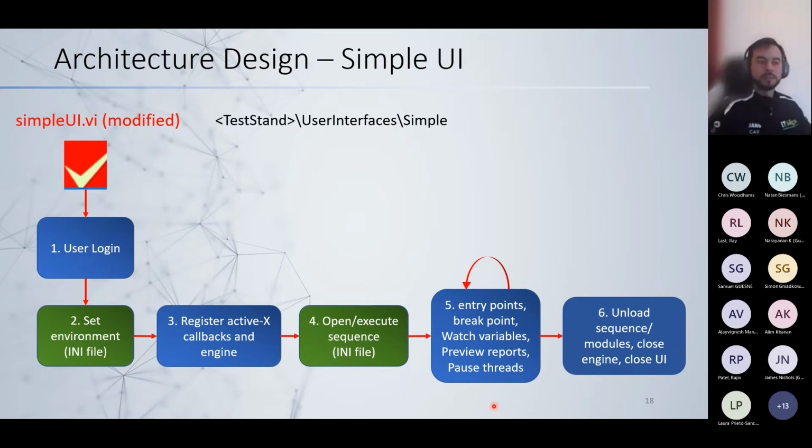Lastly, if you want to shut down your application, there's more modification I have done just to communicate this QMH side to this simple UI. We tried so hard to keep them separate that I'm going to show the strategy. This VI is running from a subpanel inside our QMH. You really want to keep the projects separated. It lessens our problems integrating both, because one project manages only TestStand-related things, and the other project manages any UI-specific stuff that we have.